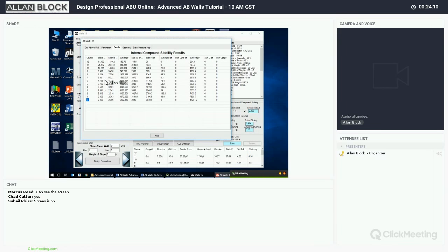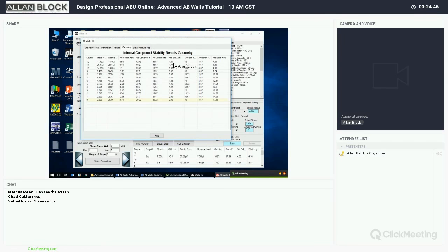I don't have a seismic load, so they're equal. So you can see everything for me is 2.3 or greater, which is great. I can get the sum of each load. Notice that if I walk across here, I've got my pressure going for it and against it. Here's the shear strength. Here's the sliding of that soil. The grid capacities, notice some of them are zeroed out, which is fine. It doesn't mean that the grid's not working. It just means that particular slip arc is not hitting that layer of geogrid. And we'll note that on that bottom layer one here where it's zeroed. And then the geometry of that slip arc too. So you get the radius and entry, exit points and that kind of stuff.